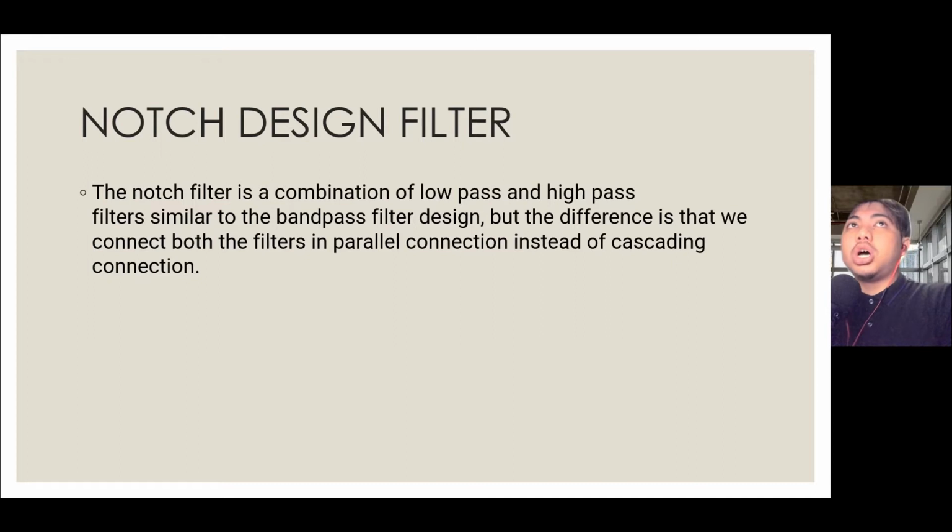The next is the notch filter design. The notch filter is a combination of low pass and high pass filters, similar to the band pass filter design, but the difference is that we connect both filters in parallel connection instead of cascading connection.